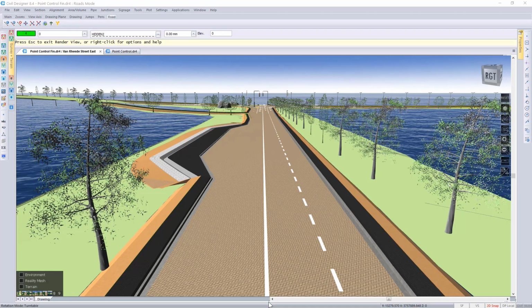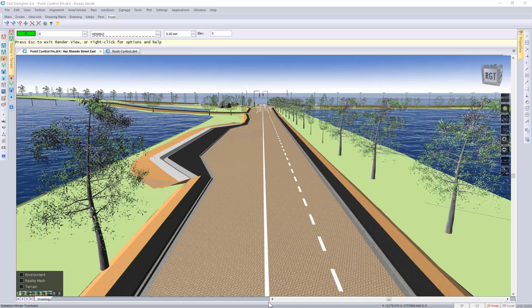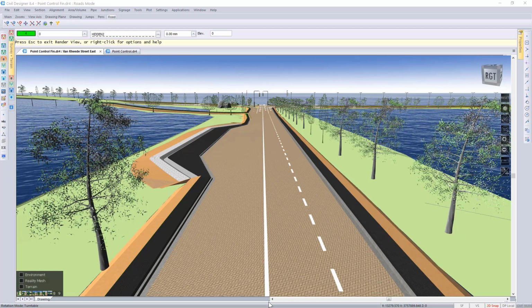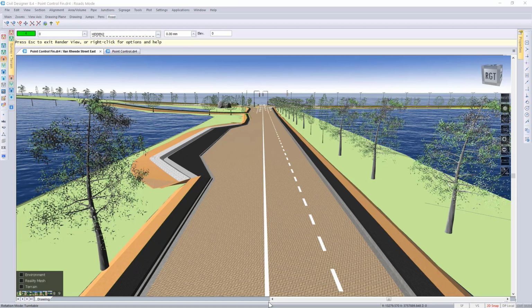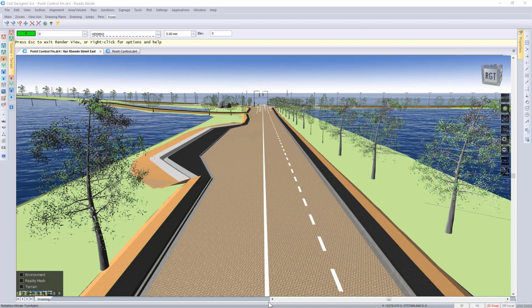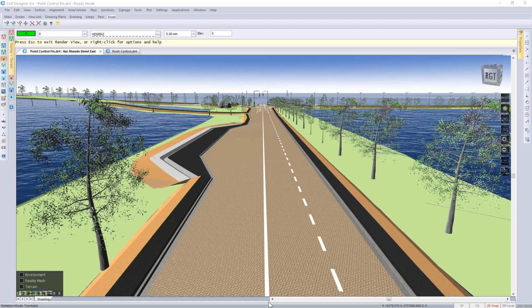I'm excited to show you the powerful point control functionality. Point control is a point that is indicated in the cross-section of your template. You are then able to modify the point horizontally or vertically, targeting a CAD entity or an existing road string. This then allows the location of the cross-sectional points or components to be moved as per your rules specified.